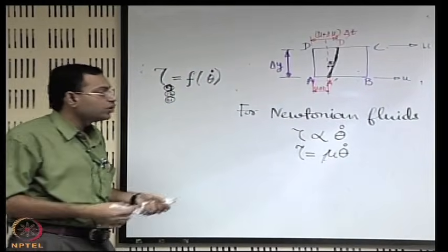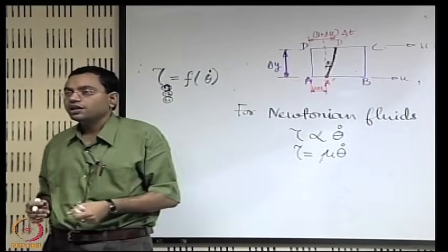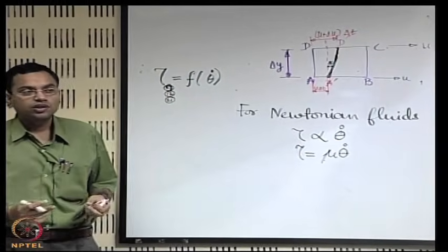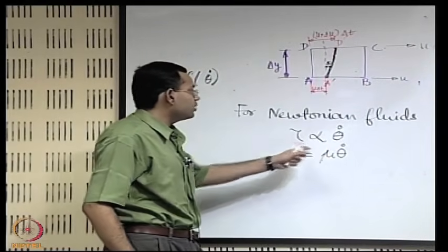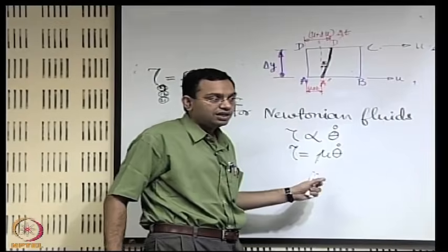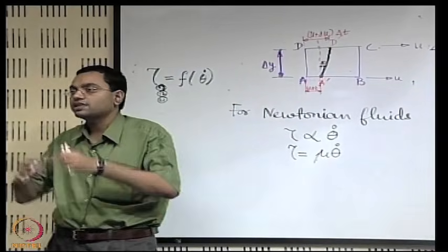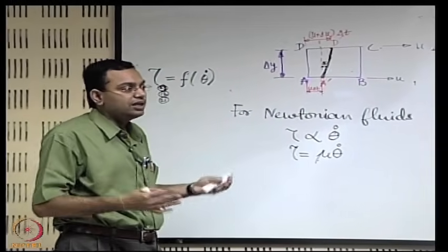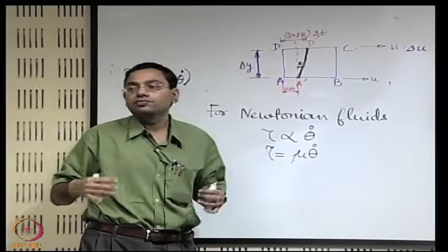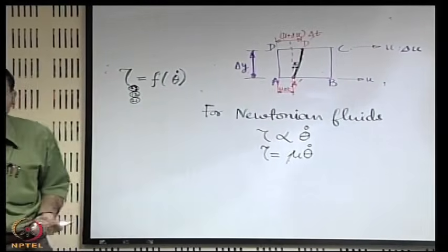The fluids which do not obey Newton's law of viscosity are known as non-Newtonian fluids. It is an entire branch of science which deals with how the material should respond in terms of its shear deformation behavior, and linear relationship is just a small part of that. The entire science is known as rheology, where you are basically dealing with the constitutive behavior of fluids against various forcing mechanisms.